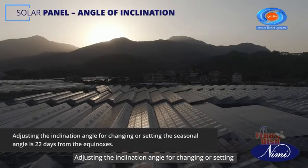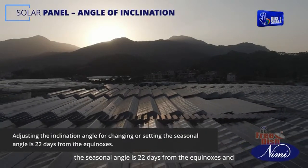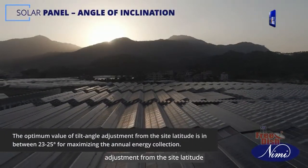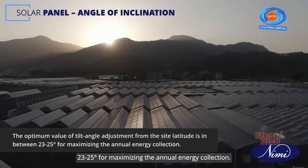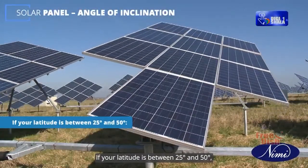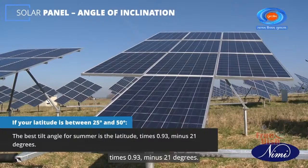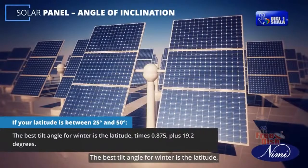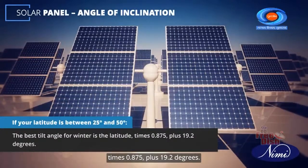Adjusting the inclination angle for changing or setting the seasonal angle is 22 days from the equinoxes, and the optimum value of tilt angle adjustment from the site latitude is in between 23 to 25 degrees for maximizing the annual energy collection. If your latitude is between 25 degrees and 50 degrees, then the best tilt angle for summer is the latitude times 0.93 minus 21 degrees. The best tilt angle for winter is the latitude times 0.875 plus 19.2 degrees.